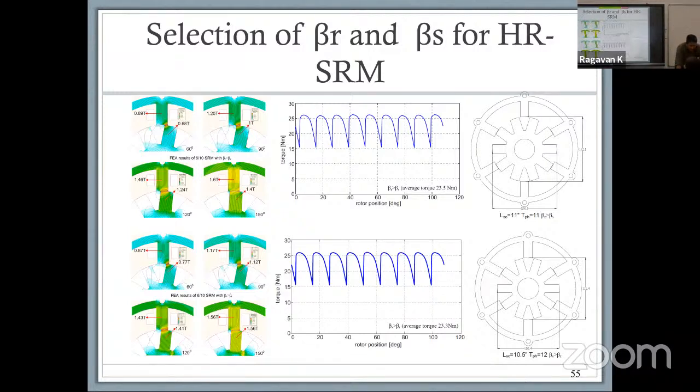And that essentially means that your magnetic flux density at your rotor pole can be smaller in a specific scenario than it is for the stator, which means that beta S larger than beta R gives you more flexibility if you want to have a complex design. So if you want a complex design, then the condition of beta S being larger than beta R can give you more flexibility in getting the machine design and a compact size. Okay, so also because you have a higher number of poles, a smaller pole arc basically will give you the same area for a given number of stator arcs.